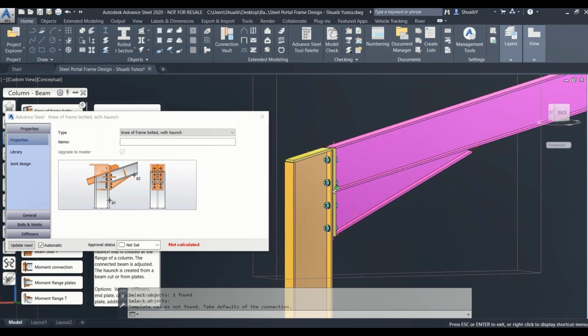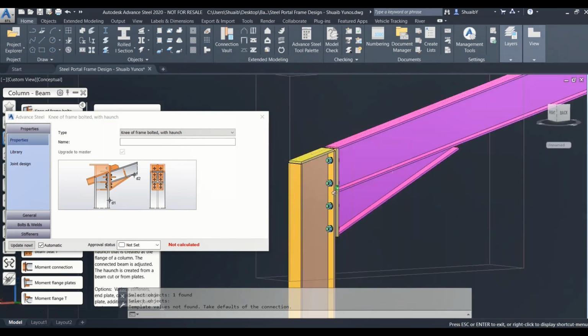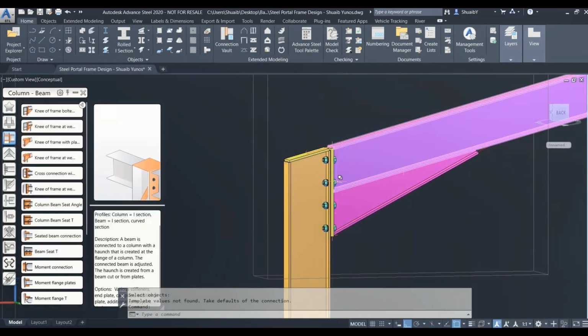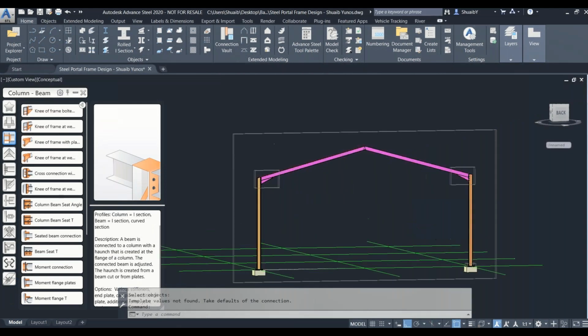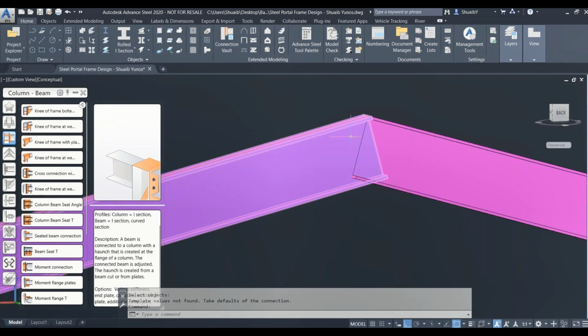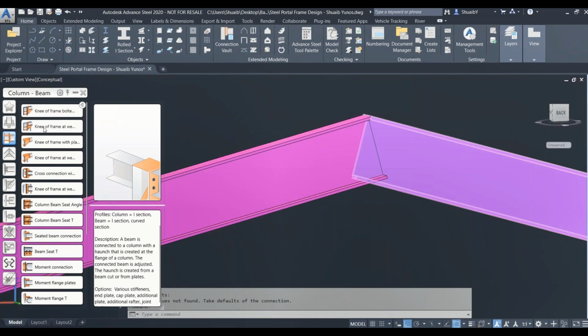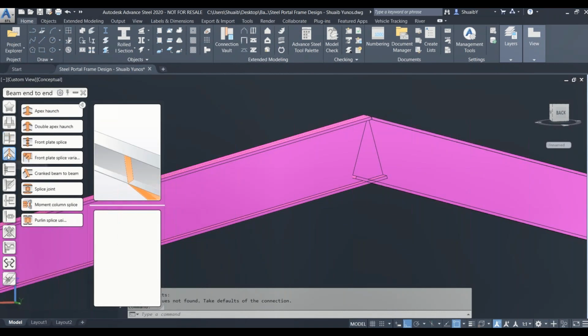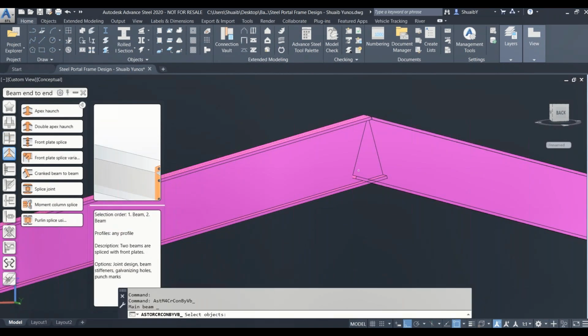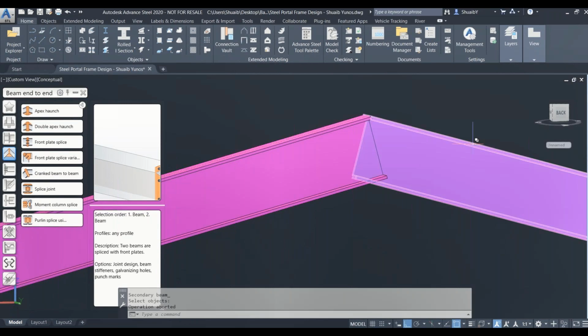Again, it's very visual. So if you're looking at it and you don't know what dimension you're dealing with, please have a look at the infographic that comes attached. And now the last part is to do the apex. Okay, so we're going to go there to the apex beam end, right? We're going to say apex haunch. We're going to select our 2 intersecting elements, structural steel.